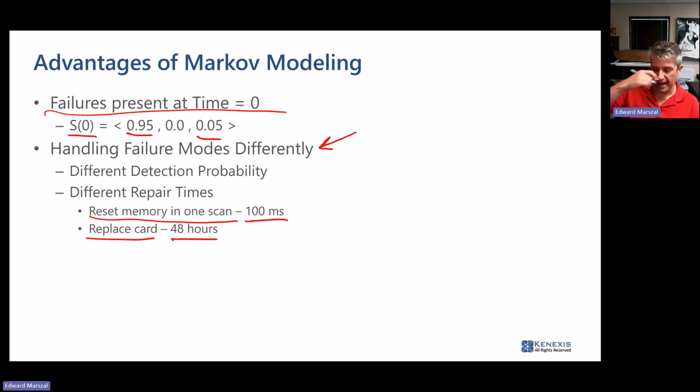All right, so one last note on Markov modeling. As I mentioned, a lot of the equipment vendors have Markov models for developing their logic solvers. Now, as you know, if you run Markov models, the probability that the SIL3 certified logic solver is the weak link in your calculation is effectively 0. Most of the time, the PFD of the logic solver is much smaller than the significant digits of the calculation as a whole and disappears from the PFD of your safety instrumented function.